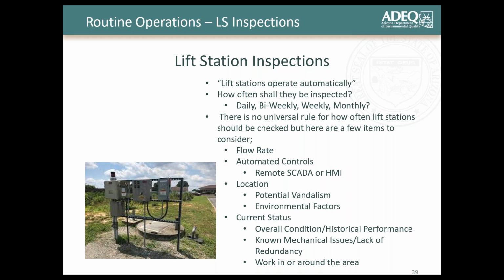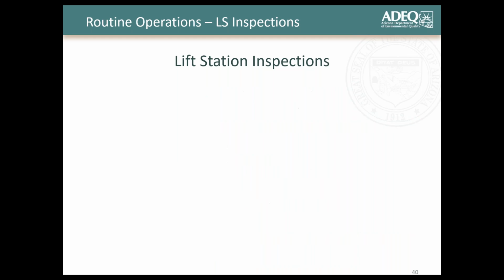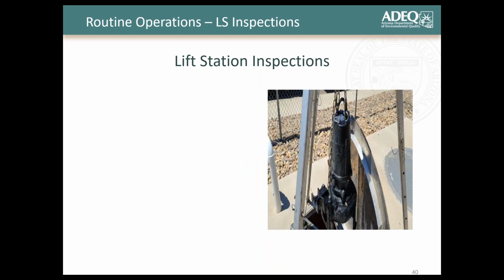If you know there's a current mechanical issue and you don't have the redundancy, then this may go from a weekly or bi-weekly check to, hey, we want somebody to drive by daily and just see how that one pump or these pumps are running till we get our redundant pumps there. If there's certain work happening in the area of that lift station, like a grading project or a lift station rehab or rebuild, the frequency of your lift station inspections is going to change and be a little bit more frequent now.